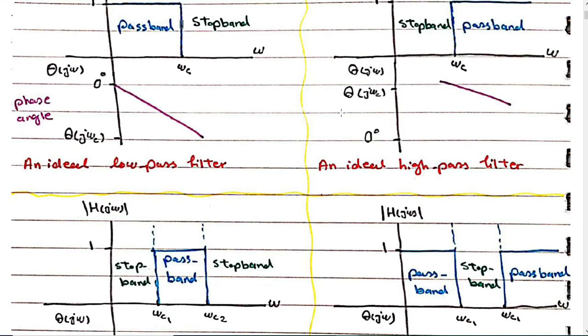So how do you calculate the phase angle for a filter in the frequency domain? Isn't that like, you have the transfer function and it's the imaginary part over real part, tan inverse, yes. Okay, so if you want to calculate the phase angle, first find the transfer function. From the transfer function, get the tan inverse of the imaginary part over the real part. Any questions?